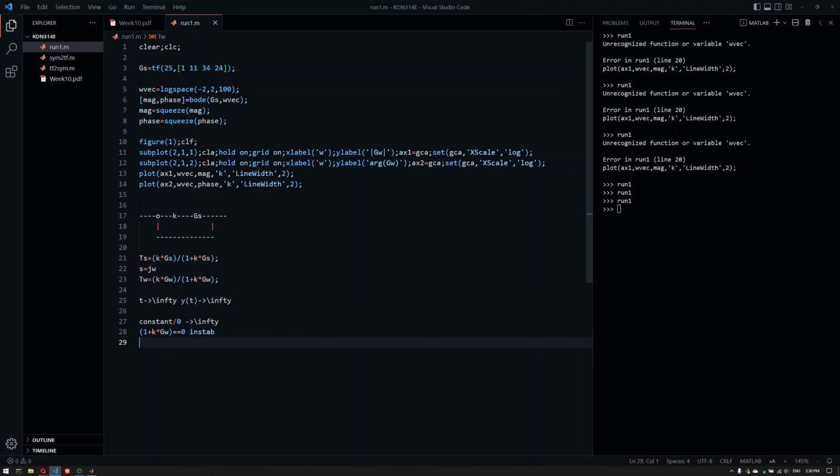What we first of all need to remember is the fact that G(jω) here is complex, so it's an element of the complex values. If this is equal to 0, I can move this 1 to the right-hand side and it becomes -1. Since we are not in Cartesian coordinates and like to use the Bode graph, we like to use polar coordinates.